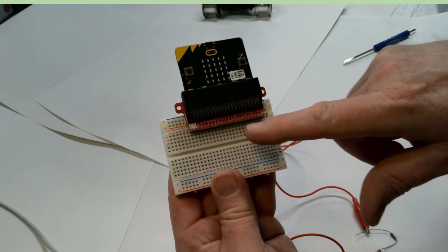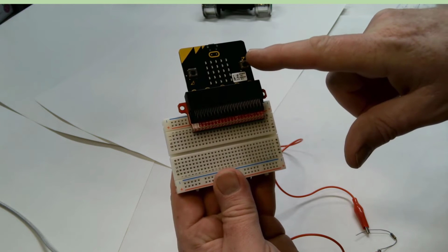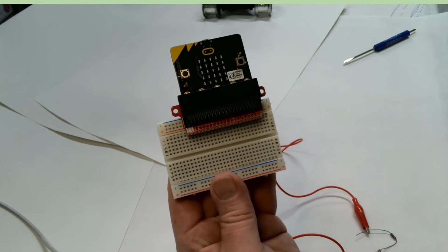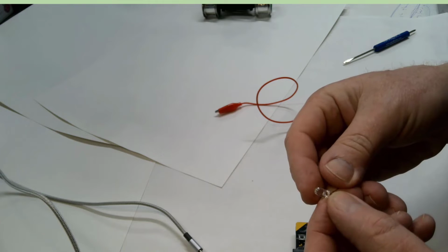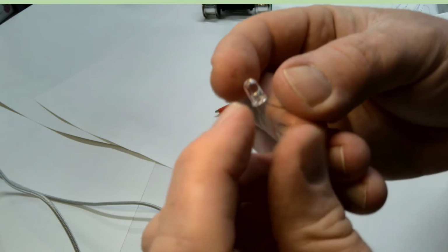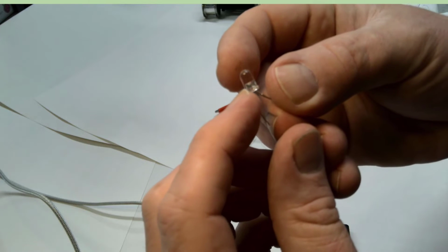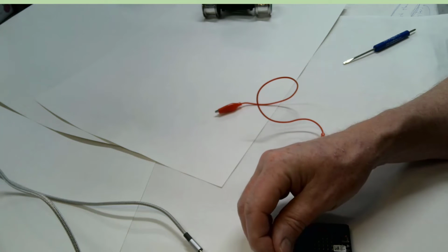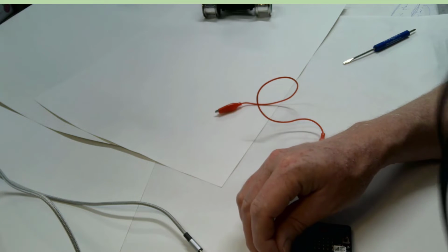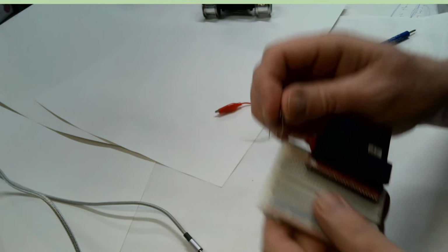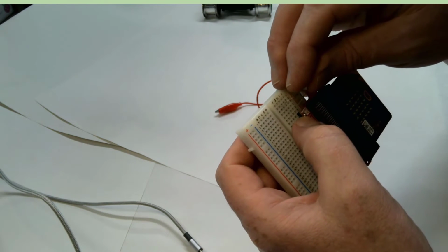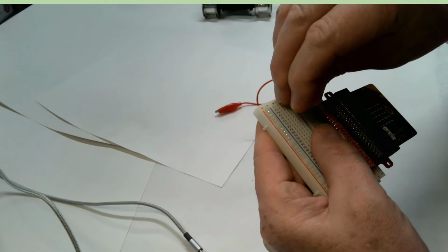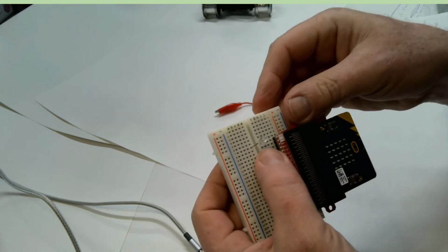So let's wire our LED circuit up to the breadboard, powered from the micro:bit through this breakout board, and we can see down here where the ground is and where the 3 volts is. Alright, so I'm looking carefully at the LED, and the side here on the left is the side with the electrode that looks a little bit like an upside down L. So I know I want that to go to ground, or the negative side of the battery. And on the micro:bit breakout board, the last 2 connectors on this side are both ground connectors. So I'm just going to plug the low side into the ground.